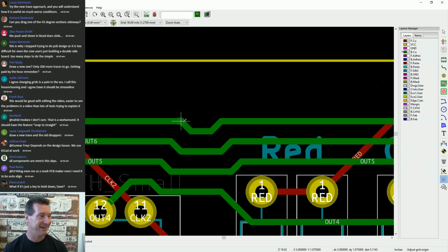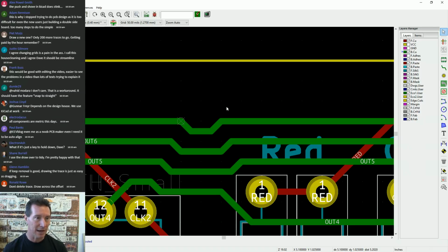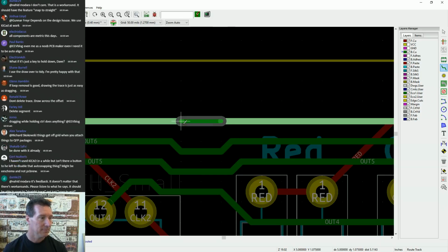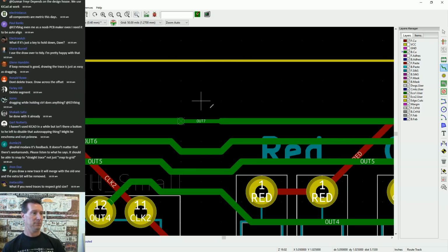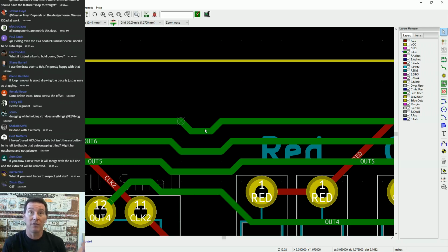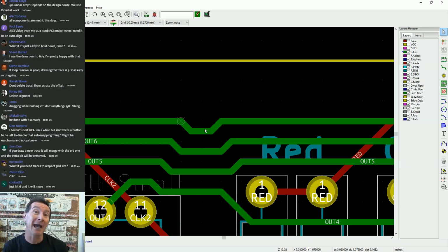Okay, I can do this, right? I'm trying to place a new track, I'm doing the X thing. Ah, there we go. Okay, it got rid of it. It's kind of groovy. Undo, but I shouldn't have to place a trace. I should just be able to drag it around. You see when I placed a trace, it was the wrong width. It didn't even do the pickup.